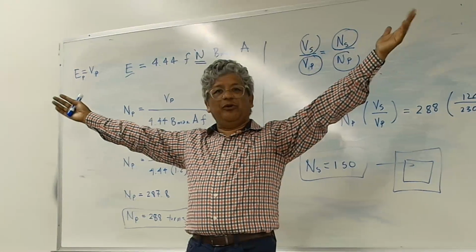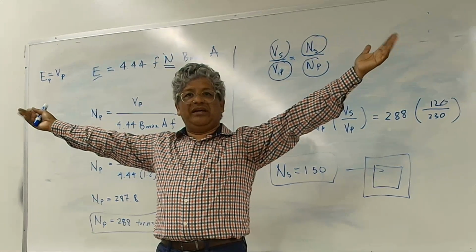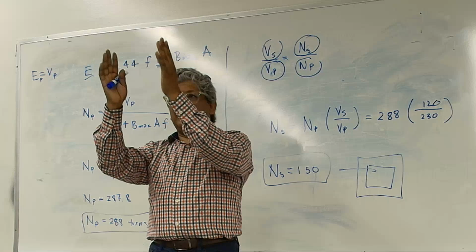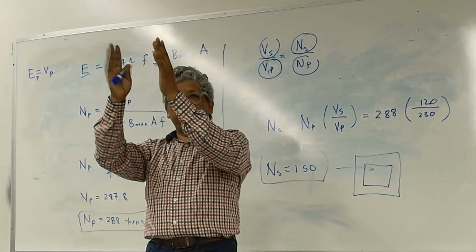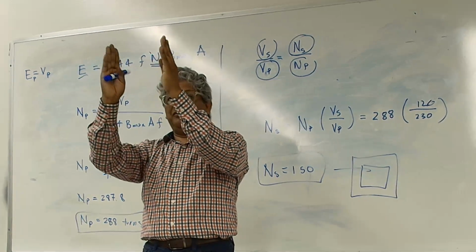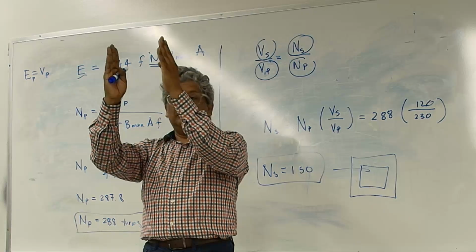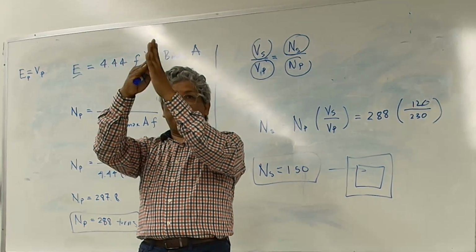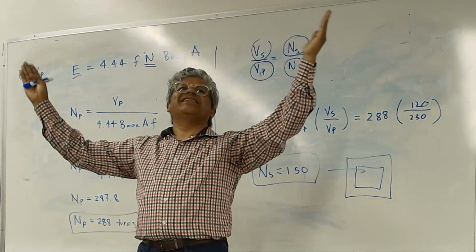The larger the voltage, the more distance you need. If you start bringing them close, you're going to have a breakdown of the insulation. What's the insulation between the two insulators? Air. There's no plastic, there is nothing, air. So you can have a breakdown, so you need a lot of spacing.